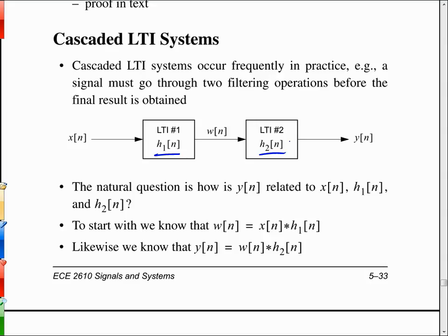We know what the undistorted waveform looks like, so there's a training sequence embedded in the waveform, and it then can design this LTI system number 2 to try to remove some of that distortion. And it does that for every frame of data that's sent. So that way, if the environment changes, it always is trying to get the best performance. And that then creates what's called an adaptive equalizer, or some sort of adaptive equalization technique.